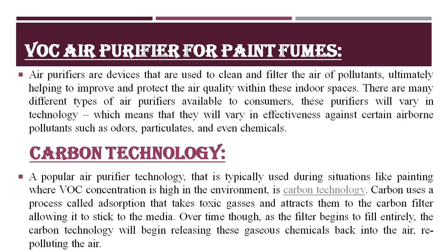There are many different types of air purifiers available to consumers. These purifiers will vary in technology, which means that they will vary in effectiveness against certain airborne pollutants such as odors, particulates, and even chemicals. Carbon technology. We can reduce VOCs from the environment with carbon technology, a popular air purifier technology that is typically used during situations like painting where VOC concentration is high.